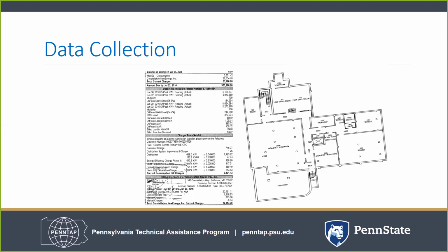After data is collected, then you start to profile the information that you have. For example, your utility bills. You want to do a utility bill analysis. Look at your facility energy assets and energy consumption. Before even considering changing out a faulty air filter, you should look at your existing energy use to understand as much as possible the existing profiles exhibited and any causal relationships you can identify.